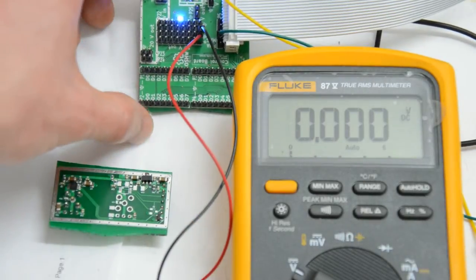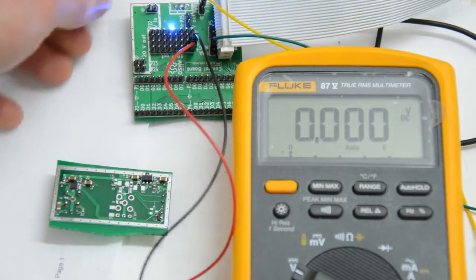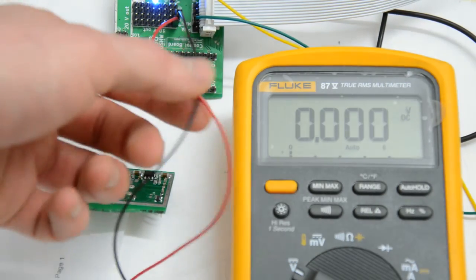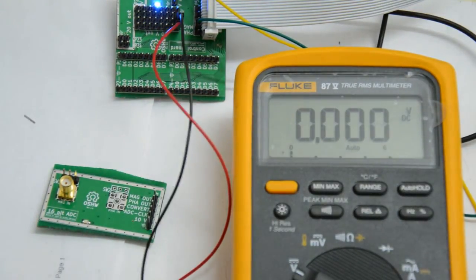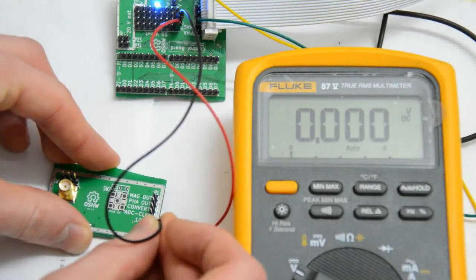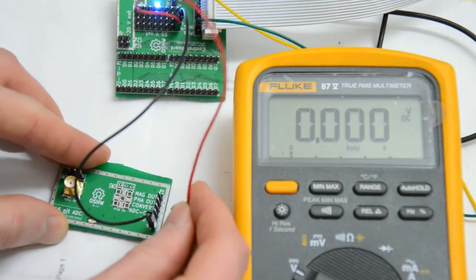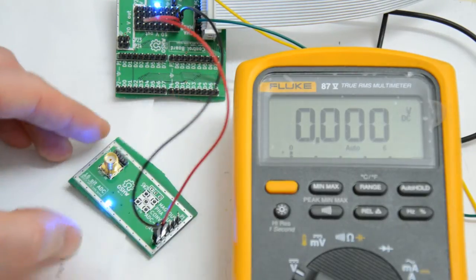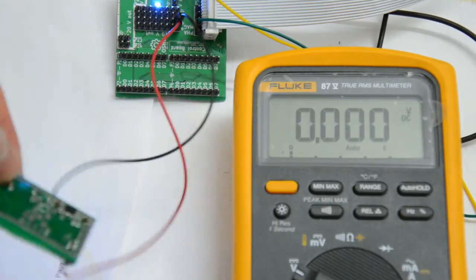That's the control board that I tested last time. So I'm getting 10 volts through these leads, and this is drawing about 1 milliamp right now. I haven't tested it yet, so I will see whether this works. I'll power it up right now, and because I haven't tested it, as usual, this means that if you see blue light, that's fine, but blue smoke is bad. So let's plug this in, and this is a blue light, so that's fine, and I'm drawing about 2 milliamps, so this seems to be exactly as I would expect.